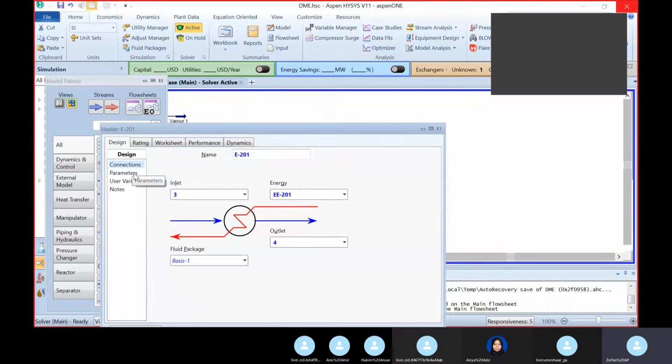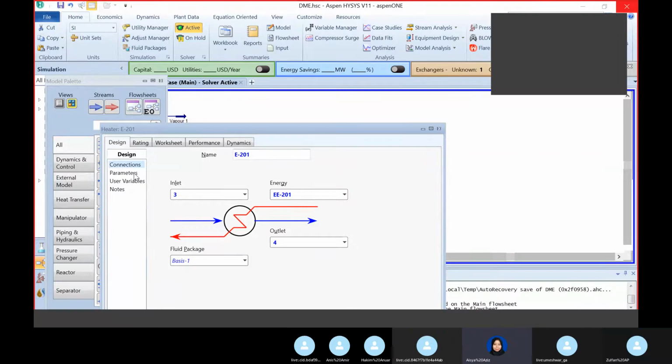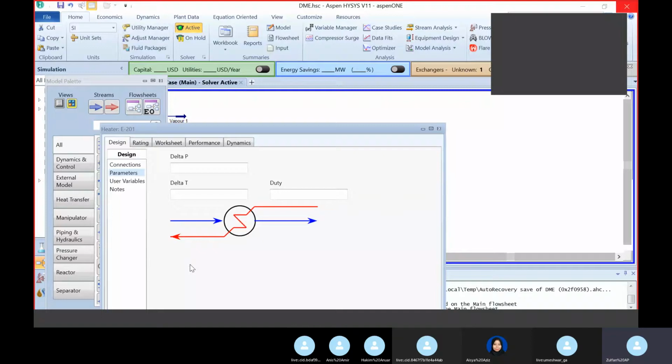You have learned heat transfer, right? Heat exchanger. So what is then the equation needed to use in this exchanger? What do you think? Molar flow rate, heat capacity, duty, delta temperature difference. Exactly. So what Shafiq writes here is Q equals mCp delta T. So we have one equation. We have four unknowns now: Q, M, Cp, and delta T.